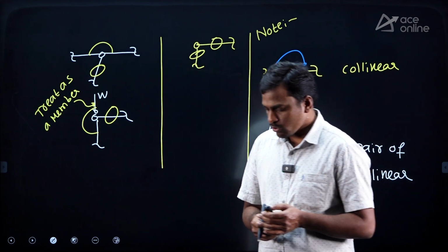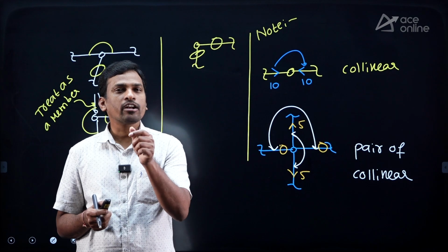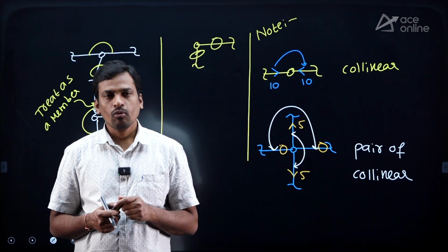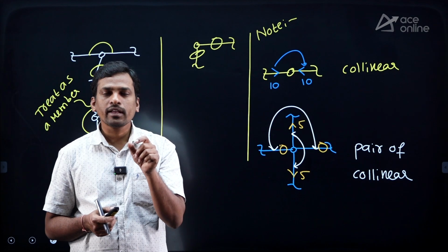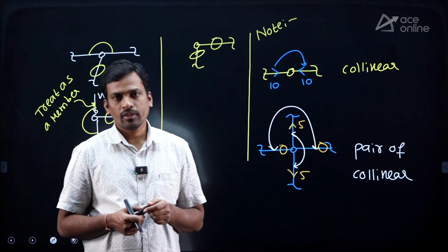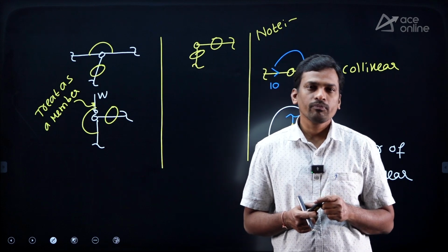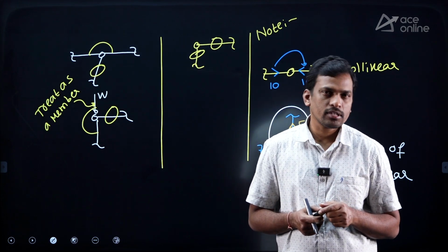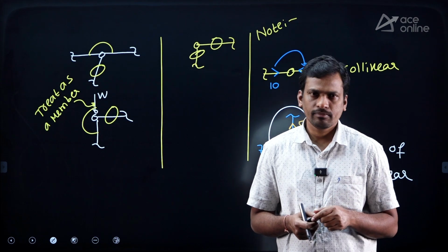And to save time in the examination, I gave preferable equilibrium equations. If I ask you to find the force in a horizontal member, the preferable equilibrium equations are sigma H equals 0 and sigma M equals 0. No need to use sigma V, it is a waste of time in the examination.